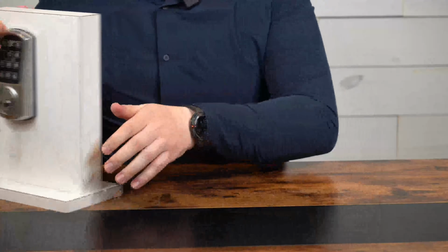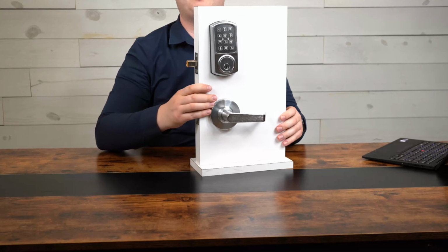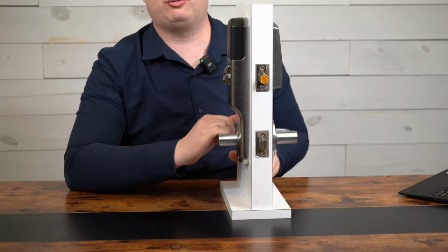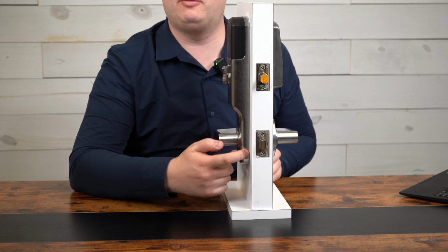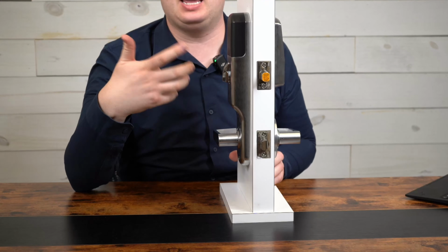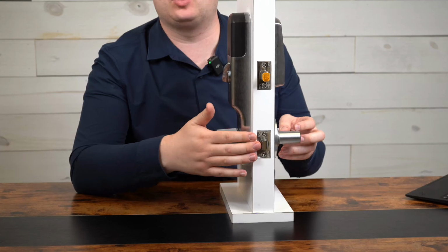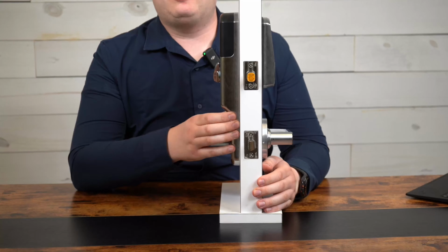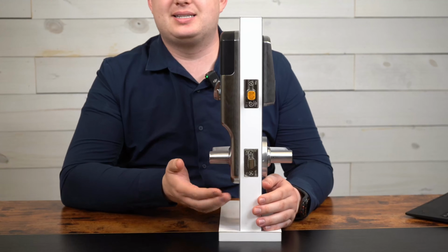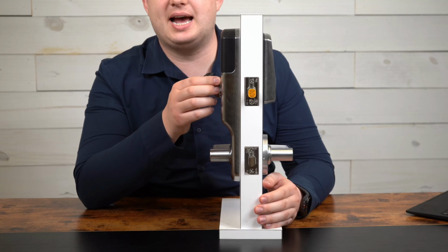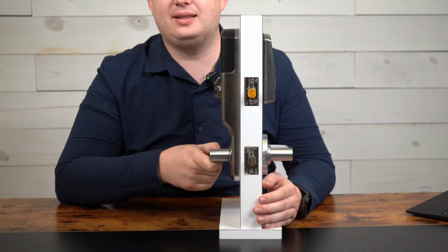Okay. Now, finally, I want to cover the interconnected beast here. Yeah, you have to zoom out for this one. So, the interconnected actually connects through the escutcheon on the outside of the door. And I want to emphasize that because if you have something like a mortise or if you connect something on the inside of the door, it's going to be a very different installation process compared to this. All of the interconnected components are inside of the escutcheon on the, what side is this? The secure side of the lock. And you can see it has both a deadbolt and it has a latch bolt.